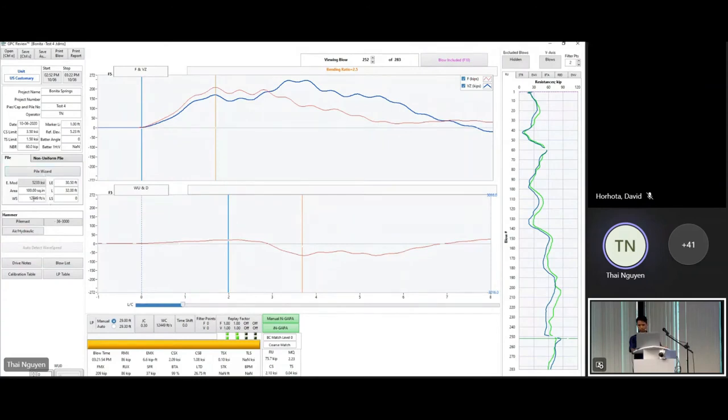The pile is only 10 inches, so even though it is 2D, it exceeds the standard. The standard calls for only 1.5D. But even though it is 2D and met the spec, because the pile is so small, the physical distance is too close.